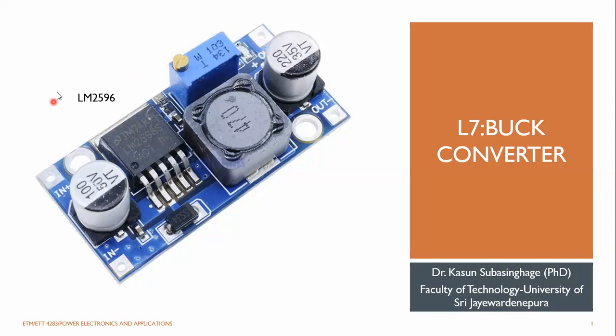Here, I have shown you a very simple example of a buck converter that you typically use for step-down conversion. You can buy it at any electronic retail shop. Basically, you feed any DC input supply to plus and minus, such as battery voltage or any DC voltage, and it converts this voltage to a stepped-down voltage and you get the output from here.